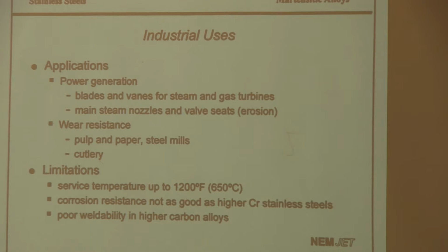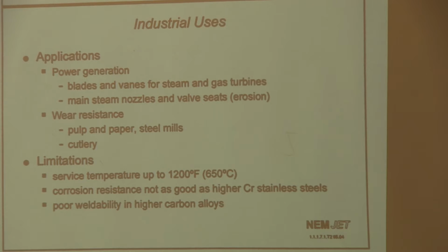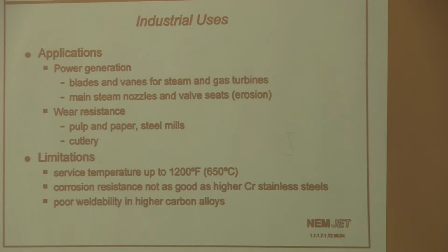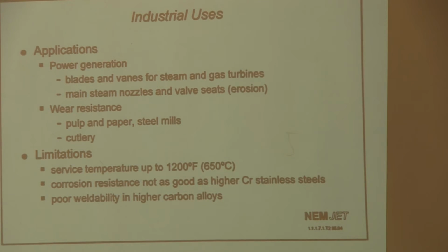I mentioned some of the limitations, the service temperatures. Corrosion resistance is not as good as the higher chromium stainless steels. And because it's a higher carbon, harder steel, the weldability is not typically as good as with austenitic stainless steels.